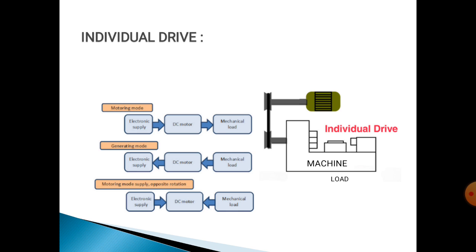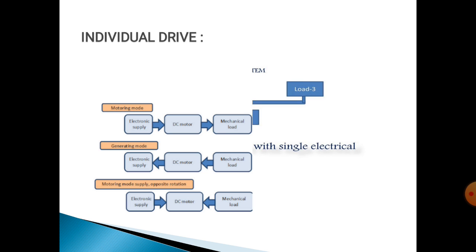The main disadvantage of individual drive is that the energy is transmitted to the different parts of the same mechanism by means of mechanical parts like gears, pulleys, etc. Hence some power losses occur. So this is the main disadvantage of individual drive.